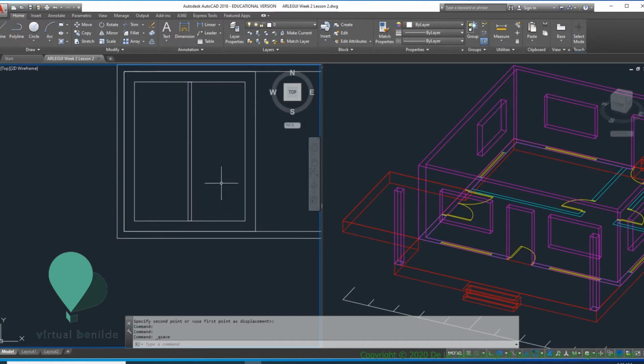Control S to save. Now I want two more of these, so these are going to be segmented into 1, 2, 3 glass panes if I have two horizontal frames. So here I need a reference line to do that and subdivide it into 3 equal parts. So what I'm going to do here is shift right click. I don't want it to be in my endpoint because I won't see that line, or the midpoint.